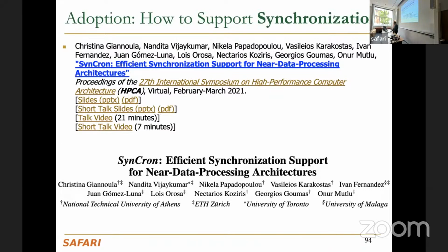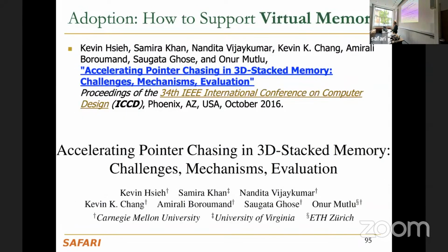Synchronization is another issue that we need to handle. I don't have time to talk about it, but there are papers. This is Christina's paper. Virtual memory is perhaps the hairiest issue. It's very hard to fix this problem, I think. How do you do the virtual address translation on the memory side without having a virtual memory infrastructure? It's expensive infrastructure. Usually what people assume is that part of the memory is allocated to do computation on the memory side, and the translation is simple in that part. That's one way of doing it, but it may not be the best way.